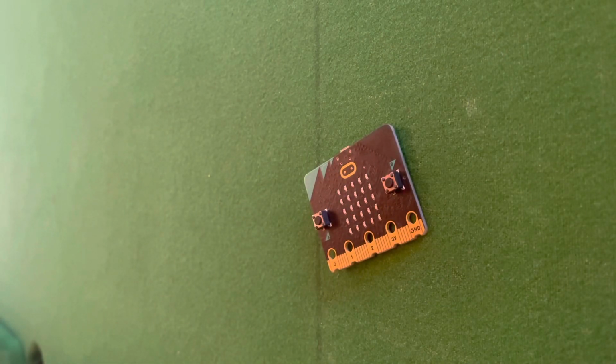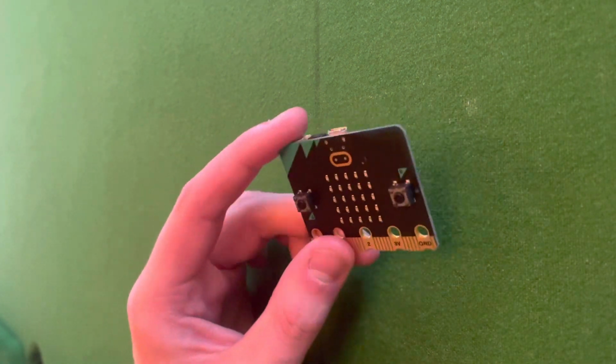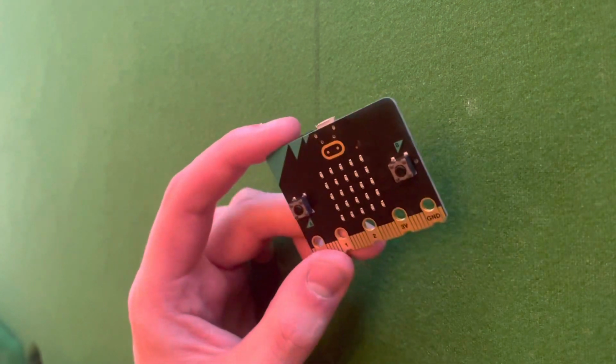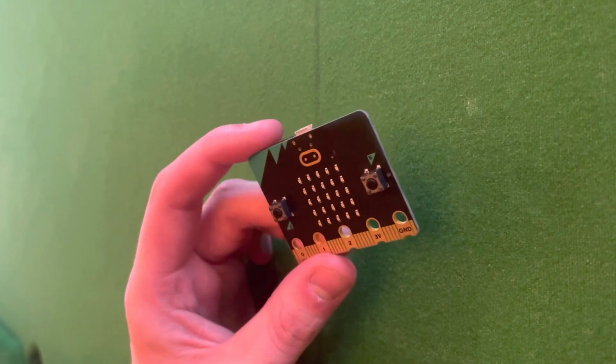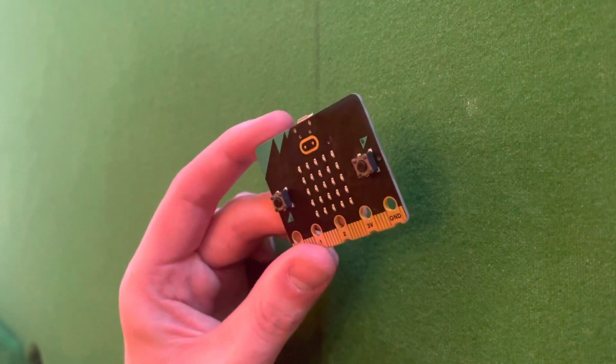A microbit is a very handy device to consider for the design of our projects because of its wide range of ability to do stuff. If we take, for example, how many different ways can one microbit activate an LED? It can either activate it by shake, or we could set a certain threshold of noise, and if this threshold is reached, an LED could be activated.